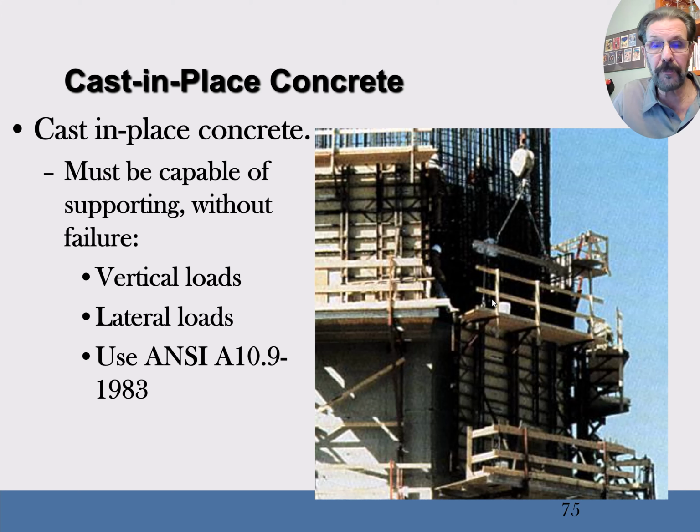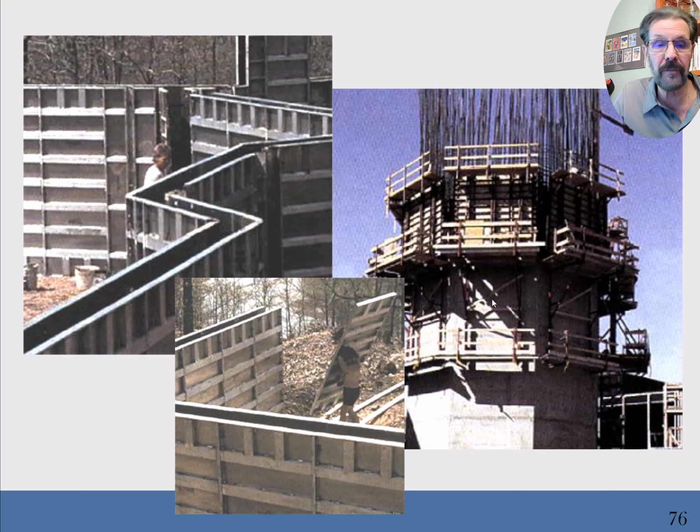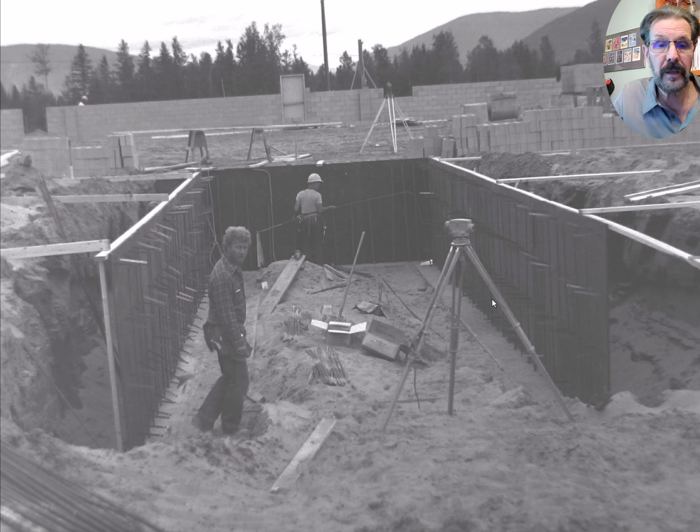There's some more slip forming going on here. There's some more of that, and some steel basement walls. There's a basement wall being formed of some kind with the old-fashioned form ties that I hate so much, that are made of sheet metal. They're really, really hard on the face when you get them in your face or in your eye or whatever. So once you get those form ties in, you want to be ready to put the other wall side form in there as soon as possible, so you're not going to be hurt, torn up.